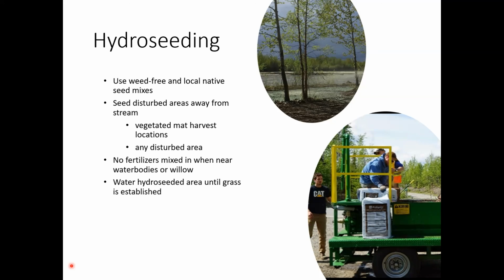Hydroseeding is valuable in that the slurry protects and holds the seeds and soils early on. It helps keep moisture in, and it jump-starts the establishment process. And it's also relatively cost-effective when revegetating large areas. Most types of native grass can be applied via hydroseeding, including a few forbs, though admittedly we have quite a bit to learn about native forb establishment with this method.